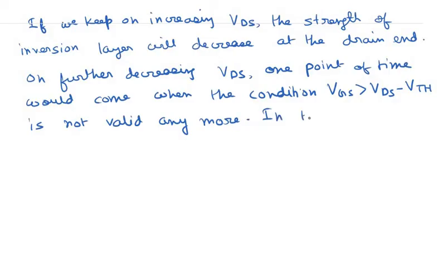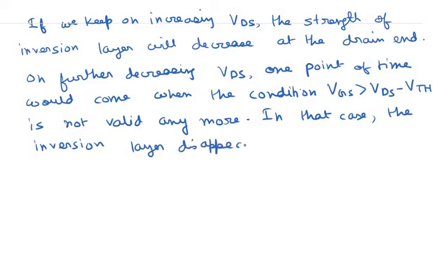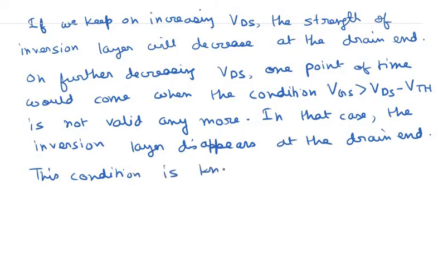In that case, when this condition is not valid anymore, the inversion layer disappears at the drain end. This condition is known as pinch off in case of MOSFET.